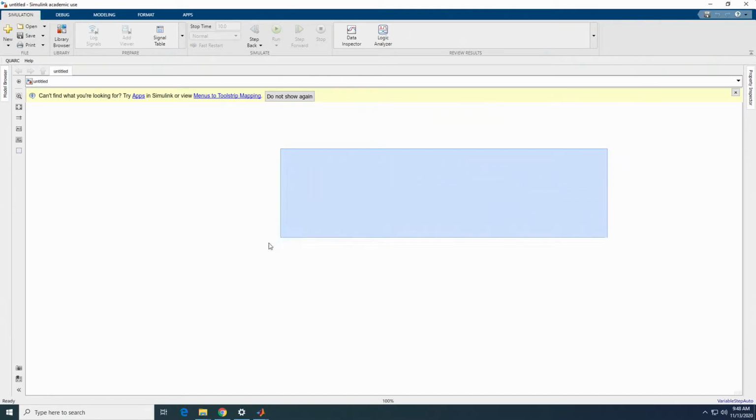In this blank space here, we will be creating a block diagram and import whatever blocks that we want to work with. So the first step when working with Quanser Servo cubes is to import the block which is called HIL Initialize, which is an interface between the Simulink model that we will be creating and the QUBE Servo.